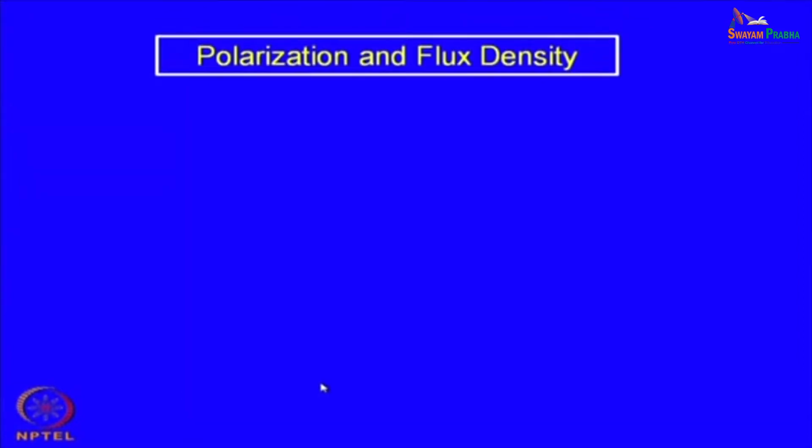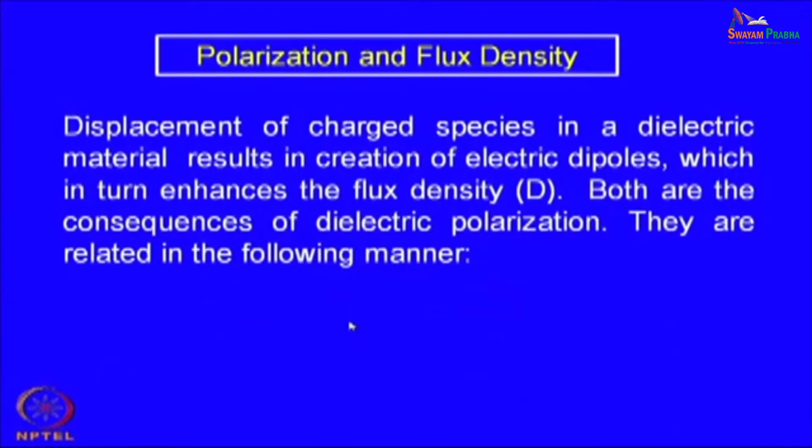This is an important phenomenon of a dielectric material. Polarization is a very common and very important phenomenon whenever we are talking about a dielectric material and an electric field is applied to it. So, polarization and flux density: displacement of charged species in a dielectric material results in creation of electric dipoles. That is what has been discussed, which in turn enhances the flux density, so it is called the dielectric flux density. Both are the consequences of dielectric polarization.